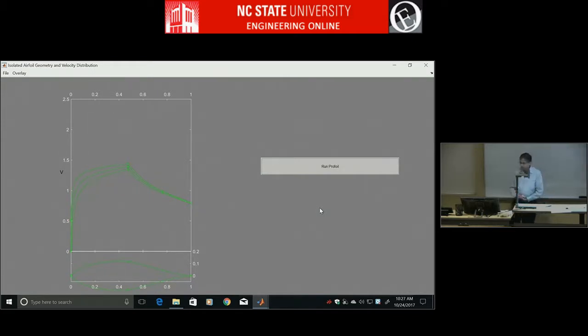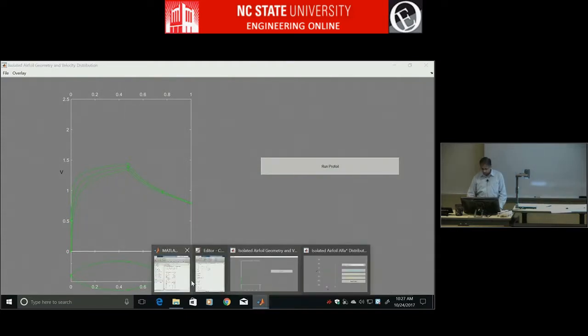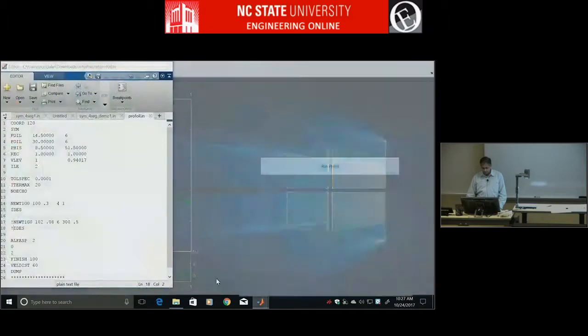segments. So you know the way alpha star works is if alpha z equals that alpha star, then you should get a flat velocity distribution on that segment, right? So I'm going to make profile plot the velocity distributions at 4 angles of attack, 0, 2, 4, 6, and so I should remember to change this to 4, and then let's run this again.